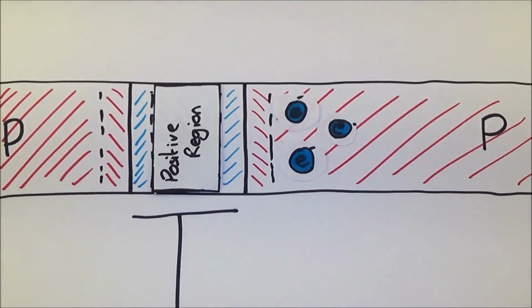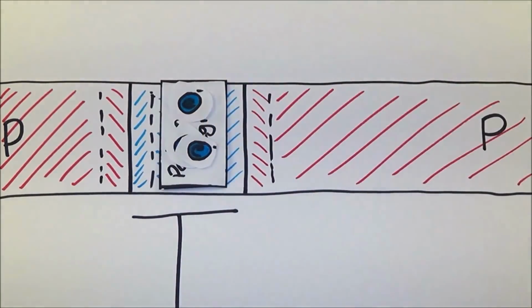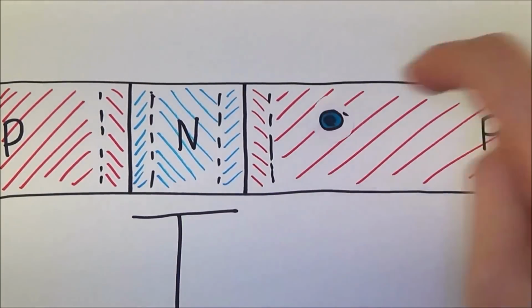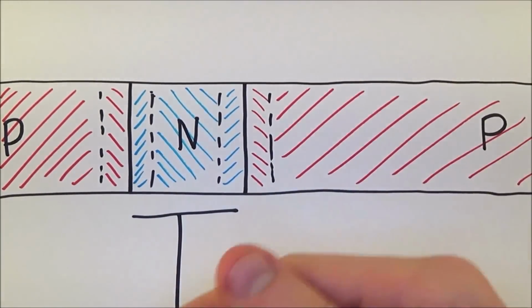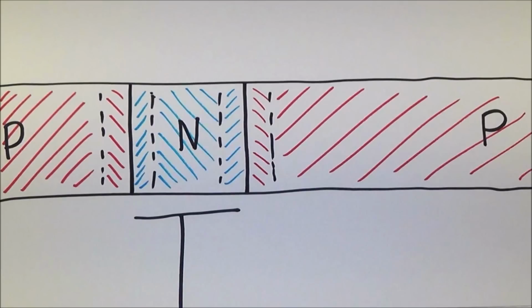If there isn't, then it forms another positive layer behind the depletion layer, so electrons can flow again, but into the N layer. Then the collector is filled up again from electrons from the power source. So the electrons move in stages, or you could see it as a flow of positive holes from the emitter to the collector. I find PNP transistors harder to get my head round compared to NPN transistors.